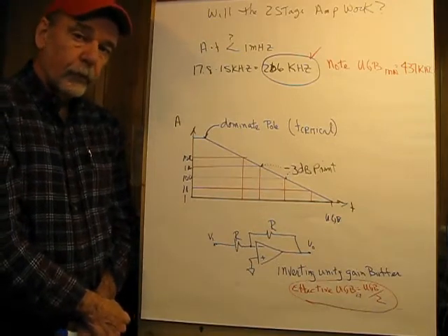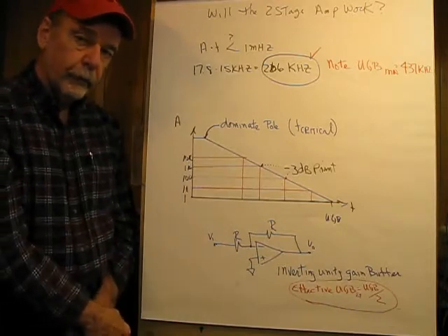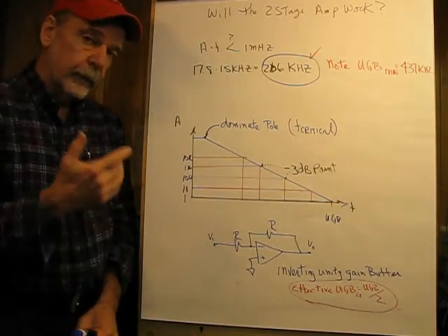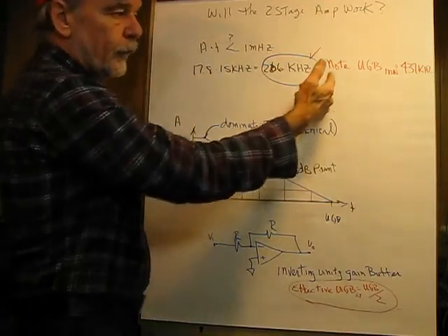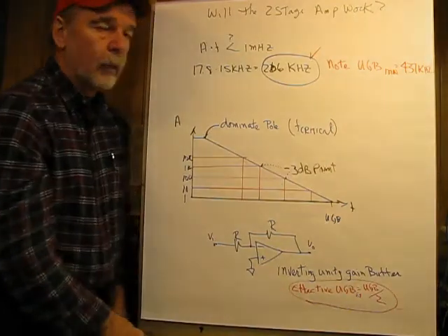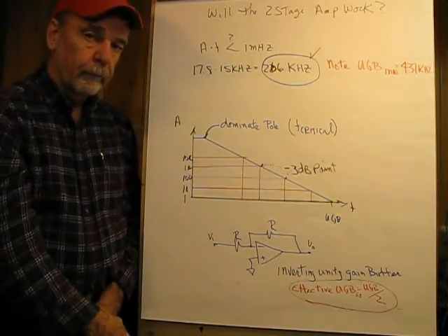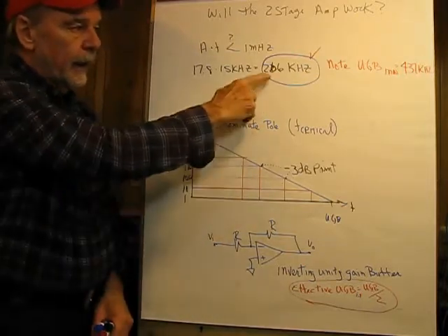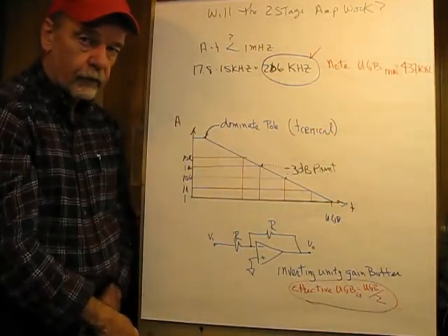So it appears that we won't be crashing into the wall, so to speak, with regard to our unity gain bandwidth. Now, remember that when we opened this little dialogue, what we said is the unity gain bandwidth minimum was 437 kilohertz. That's your design spec. You used a minimum gain, and this here is less than the minimum, so this looks like a safe design.